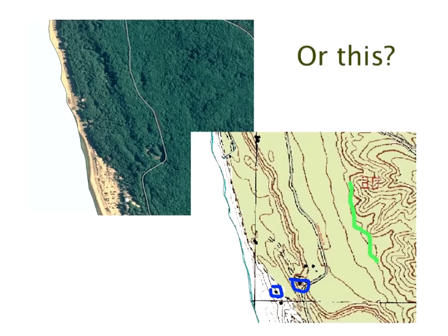Yeah, these GPS maps are very, very useful indeed. They can tell you where you can't put in a system, but they can never really tell you where you can put in a system. In other words, you need to go on site to look at the specific detail. Sometimes they'll show you a wetland or a high water table, or a big gully where the rain obviously comes pouring down. There are some areas that you must avoid. But typically, there are lots of systems all the way down the coast.